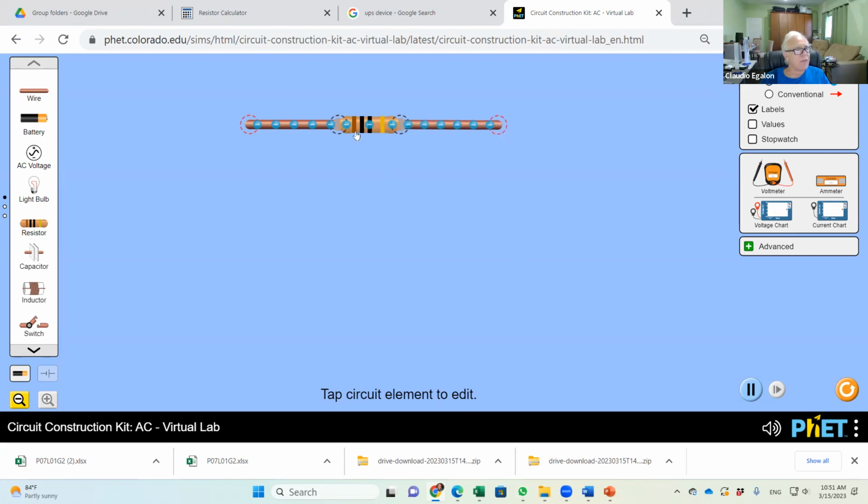Okay, look at the bands of your resistor, brown, black, black, right? Brown, black, black is 10 ohms. Brown is 1, 0, black is 0, 1 and 0 is 10. Black is also 0, so 10 to the 0 is 1. So it's 10 ohms. And the gold is the 5% tolerance, okay?